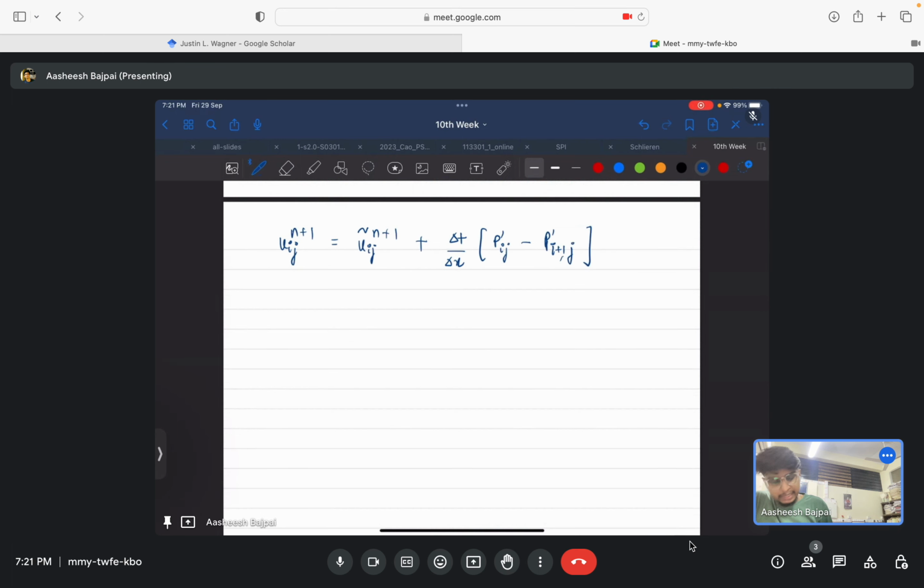This we have done. Let us do it for a step in the previous step, in the backward phase, you can say, for a backward point or backward difference method by applying that. So just putting i as i minus 1, I can do it. So let's put it i as i minus 1 comma j at n plus 1. Why am I doing it? Because I want to satisfy this with the continuity equation. So this is our next step.